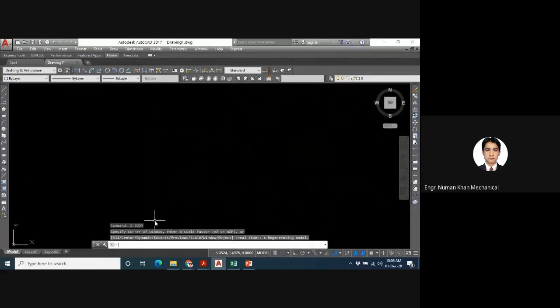But keep this in mind, you can also use the multiple command with any command. You just type multiple and repeat the name of the command. It will be doing it. You don't need to go back and come out of the command, re-enter it. You can do it. It is not that difficult.